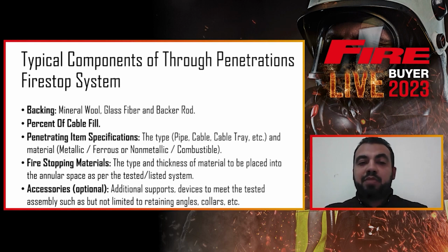The penetration item specification: every penetrant will have different behavior in the event of fire and when exposed to high temperature. Plastic pipes, metallic pipes, cables and cable trays are different, and the combustibility of the material will also affect how it performs in the event of fire.